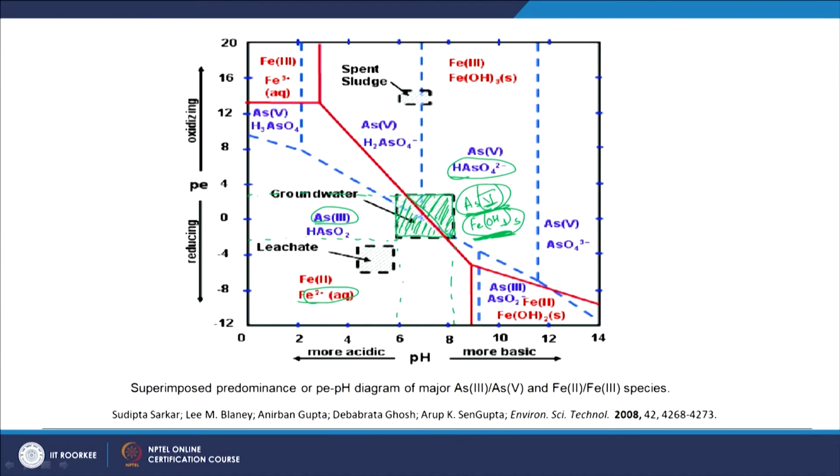Unlike the other case when we had, let us say, Fe(OH)3 and arsenic 5, we saw that co-precipitation is going to occur. So, the arsenic concentration in the water is going to be less or negligible, obviously depending upon the amount of precipitate that is available or being formed there. So, again, that is the particular understanding with respect to estimating the concentrations of arsenic, a carcinogenic, toxic compound, and such in your particular system now.